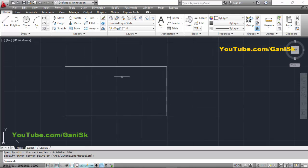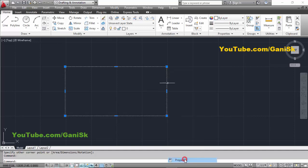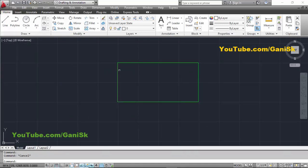Now we are going to change the color of this rectangle. Select the rectangle, then you can click here and select the color. Otherwise, select the rectangle, right click the mouse, click on Properties, click here and you can select from this option also. For example, let's take green color and close this window. Click Escape to exit the command. You can see now we have the rectangle.